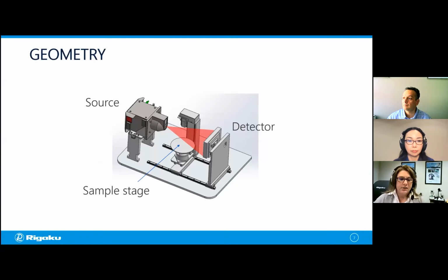So here is what the instrument would look like if we could see inside of it. So you have an X-ray source. And with regard to the X-ray source, we're going to consider things like X-ray energy and filters going along with that. We're going to be considering focus size and how that might impact some of our settings. Also inside the instrument is a sample stage. It moves and its position will change with the field of view, as will the detector, which is also movable.